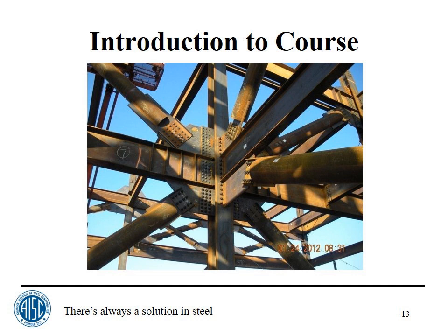The double clips have the advantage that the beam could be cut a little bit short, and you can take up the slack in the proud dimension on the clips or the setback dimension on the clips, whereas if you've got an end plate, the thing's got to be cut just about perfectly to start with, or you're kind of dead in the water on it. Shear tabs are really a very inexpensive connection for the field. They do encompass extra cost sometimes in the shop because of the number of bolts that you have to use.